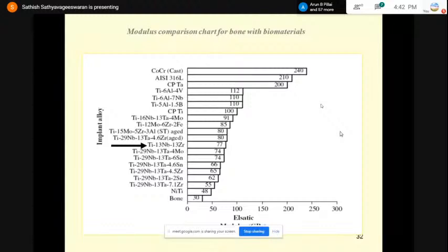And if you want to prevent that, we have to end up with some amount of unmelted particle along with the splat. If that is the case, the propagating cracks may be arrested. So in general, what I want to say is, whenever you are going for any thermal spraying process, definitely you will end up with these kinds of splats in the microstructure.